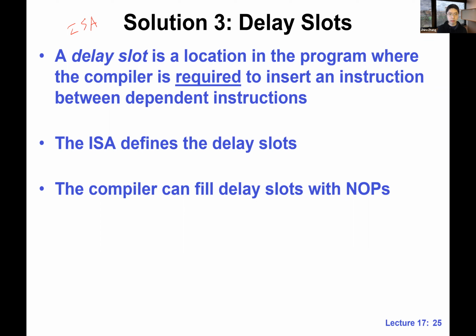Again, this is fairly abstract, but if I give you one example, right? Again, we have a load, right? With the delay slot in the ISA. Okay? The ISA basically says that with a load instruction in our 2300 ISA, the hardware will just assume that whatever follows the load is always going to be unconditionally executed, and it's not going to cause any harm.